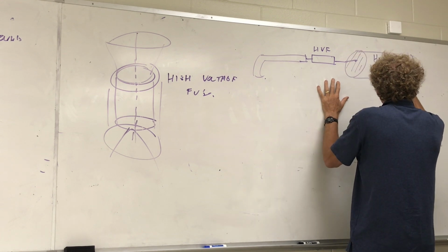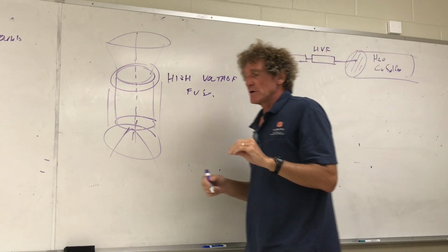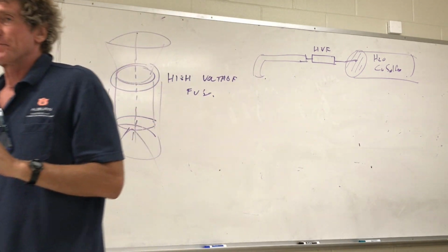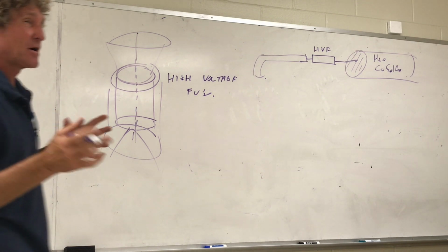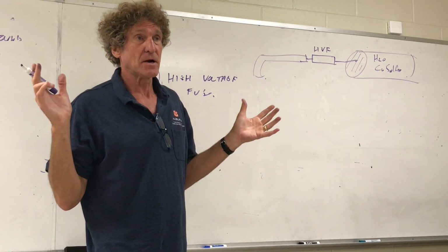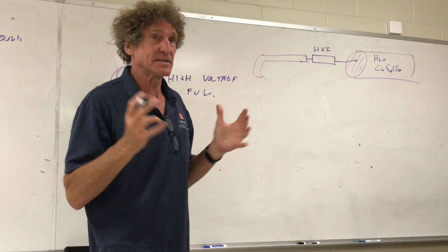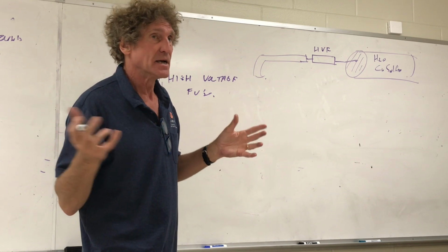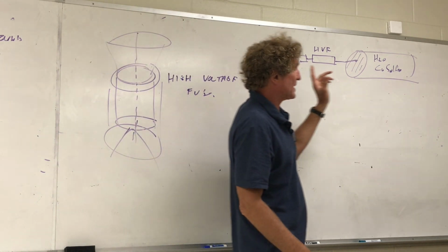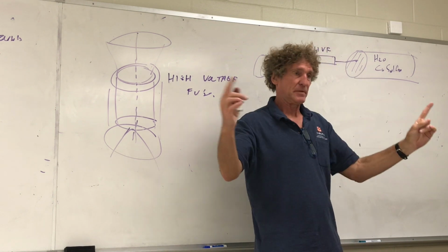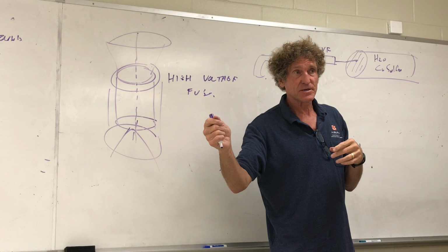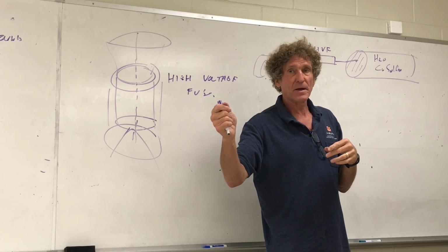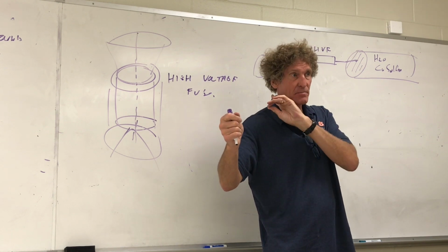Copper sulfate. And the reason we put copper sulfate, or we could use rock salt, is so it can conduct, but it's going to have a certain level of conductivity that would limit the current at 10,000 volts to be less than 10 amps. Are you with me on this? Much less. Now this water takes a lot to heat up. So it's maybe this long and that thick. After you discharge these things, there won't be an arc, there won't be a bang or anything like that because it's limited by the water resistor.